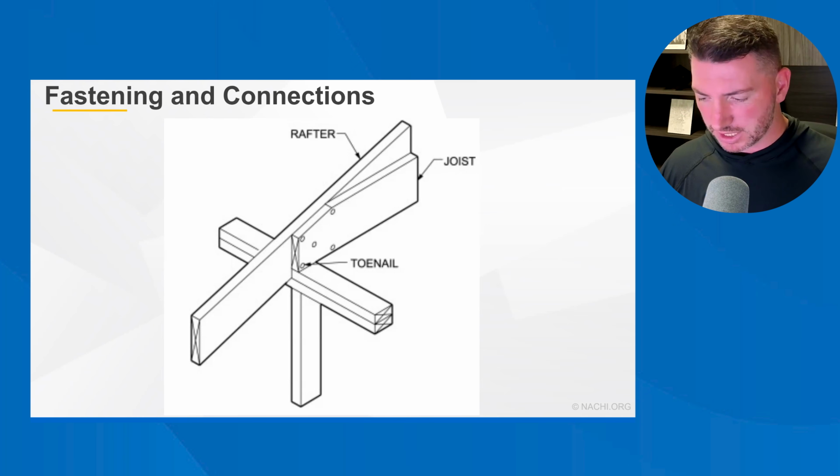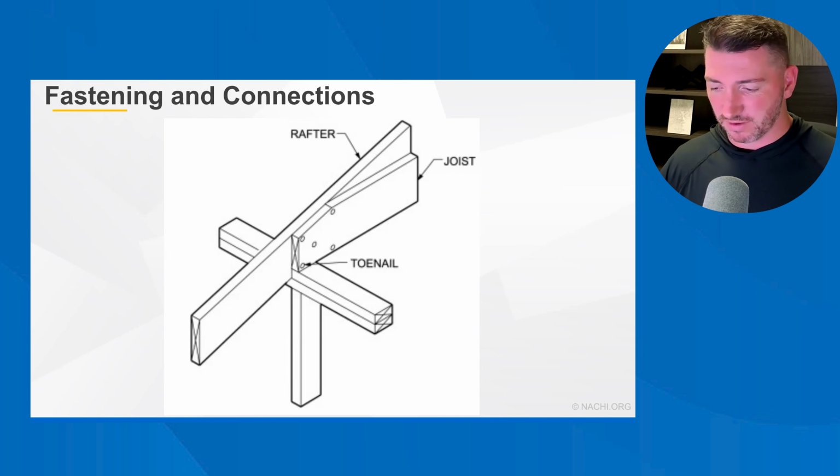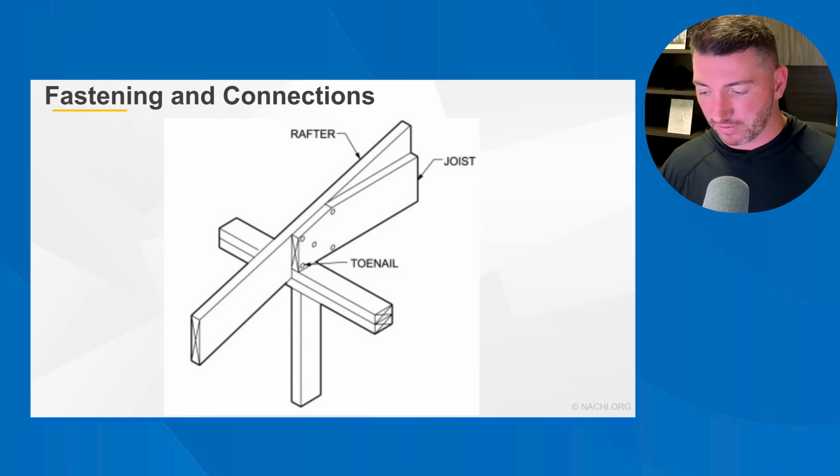For example, the IRC specifies nail size and spacing for rafter to ridge connections, rafter to top plate connections, and collar tie installations. Verifying that every connection meets code specified fastening requirements is definitely beyond the scope of a typical home inspection. You can't reasonably count nails or verify that a 16 penny nail was used instead of a 10 penny nail without destructive testing.